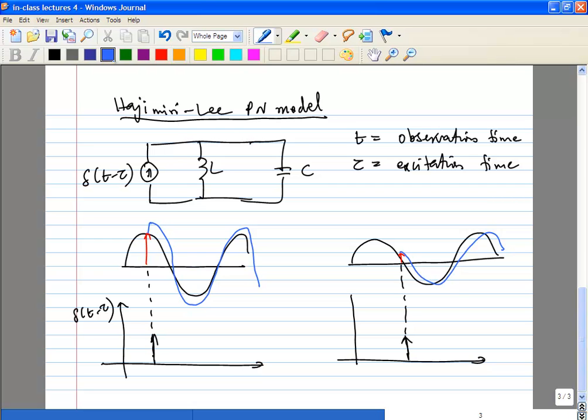For the immediate cycle the amplitude will change. Eventually, because you have an amplitude limiting cycle, it will come back to the right amplitude, in a few cycles depending on how strong that is. So if you have some AM noise, that's going to be removed by your limiter. The point to note is that it never registers; the zero crossing doesn't change, so it won't change into phase noise.